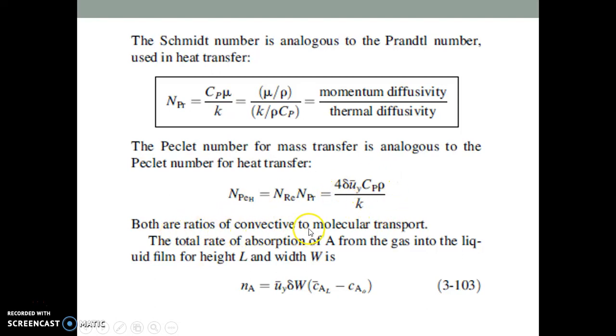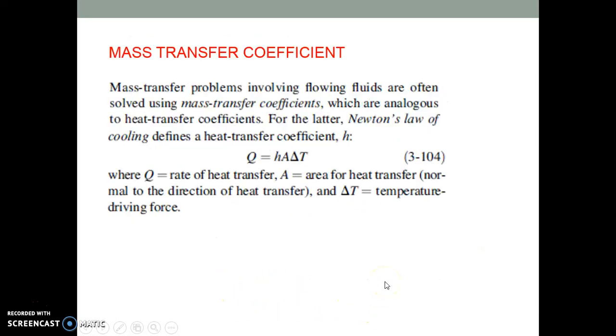Both are the ratio of convective to molecular transport, where the total rate of absorption of A from gas into the liquid film for height L and width Y is denoted by this relation. For the mass transfer coefficient, it involves the mass transfer coefficient with the heat transfer coefficient for Newton's law of cooling, defined as this equation, Q equals hA delta T, where Q is the rate of heat transfer, A is the area of heat transfer, and delta T is the temperature driving